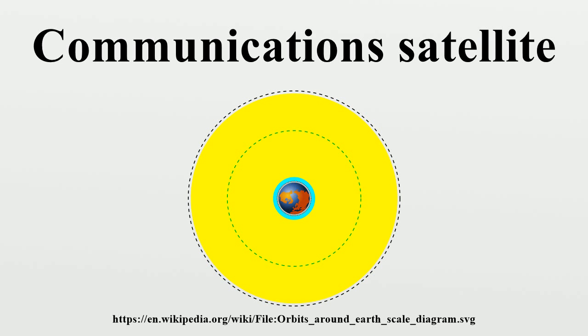Low Earth orbit typically is a circular orbit about 160 to 2,000 kilometers above the Earth's surface and, correspondingly, has a period of about 90 minutes. Because of their low altitude, these satellites are only visible from within a radius of roughly 1,000 kilometers from the sub-satellite point. In addition, satellites in low Earth orbit change their position relative to the ground position quickly. So even for local applications, a large number of satellites are needed if the mission requires uninterrupted connectivity.